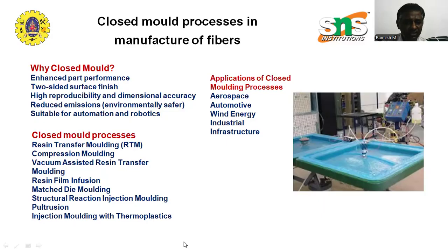In RTM, the advantages are that high quality, void-free parts are obtained. A two-sided smooth finish is obtained. It is suited for complex geometry. In terms of applications: automotive parts, aerospace parts, industrial equipment, especially automotive panels.